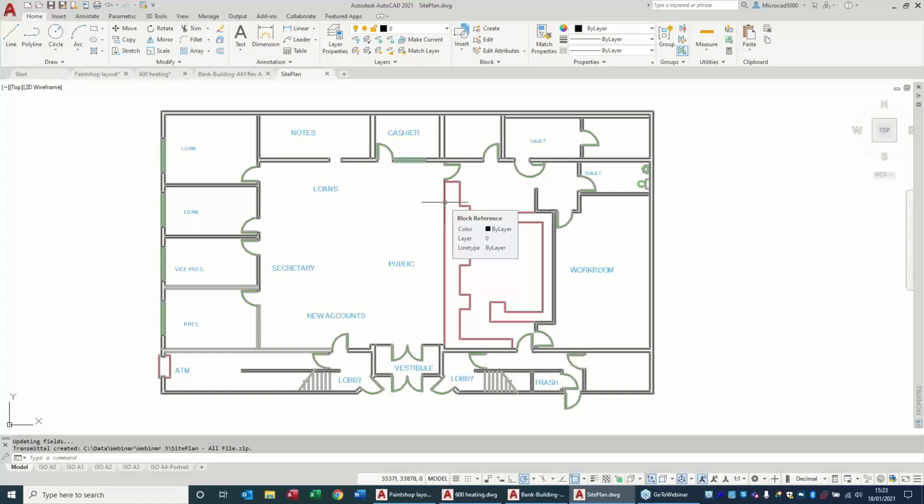And I think it's a really useful tool for saving historical revisions, because I suspect that if you were to open up a drawing file that you created on your system, say 2 or 3 years ago, when you print it out, it will look nothing like it did when it was printed out 2 or 3 years ago. But if you were to e-transmit and zip that file up with its dependencies and save it away in an archive folder, when you unzip it a couple of years down the line, you have your plot style tables in there, the fonts in there, and everything else in there.